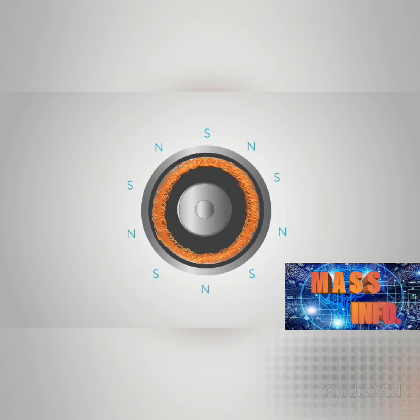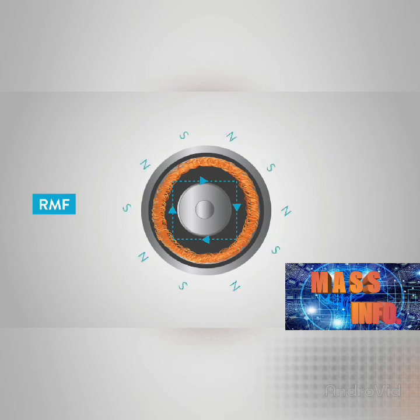The revolving flux is called a rotating magnetic field, or RMF. The relative speed between the stator rotating magnetic field and rotor conductors causes an induced electromotive force in the rotor conductors according to Faraday's law of electromagnetic induction. This is the same action that occurs in transformers.